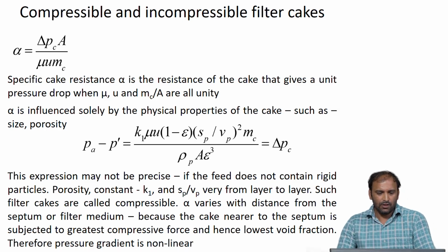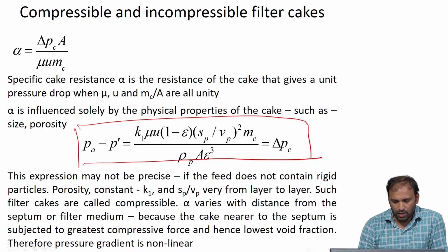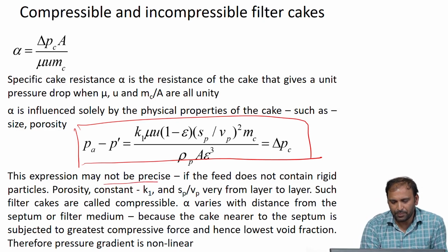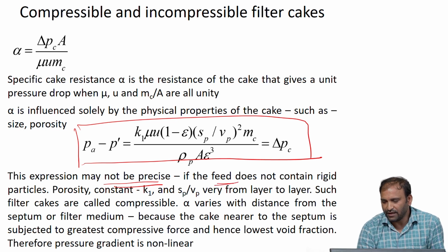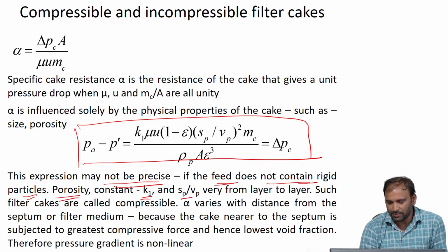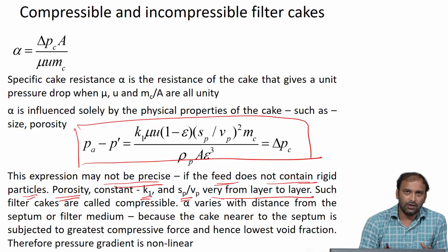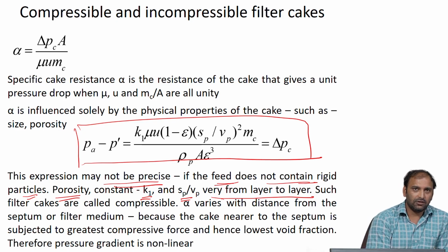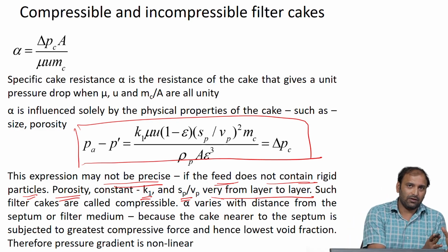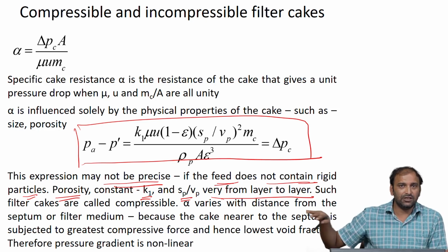So this is the expression that we have developed. As I said, this expression may not be precise if the feed does not contain rigid particles. Therefore the porosity, the constant K, and Sp by Vp may vary from layer to layer. If you look at the region close to the filter medium, if a large cake is developed, there could be a much closer packing of particles compared to the region closer to the